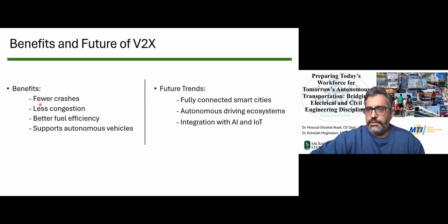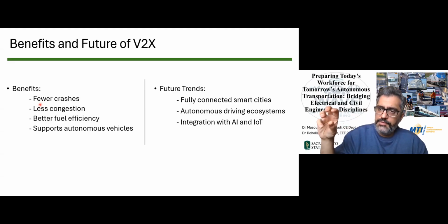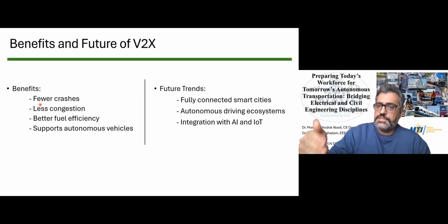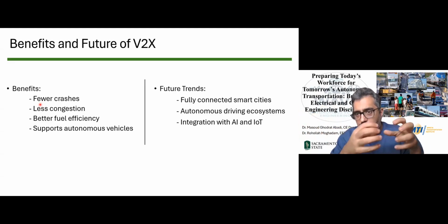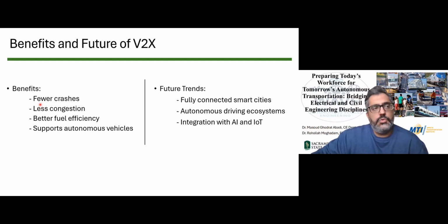If I can talk to the traffic lights, as soon as this group of vehicles arrives at an intersection, give them green. And as they are moving through the intersections, keep them moving. Make a green wave for them, signal coordination, right? That would improve the efficiency of the system, which will then help on environmental issues like better fuel efficiency.